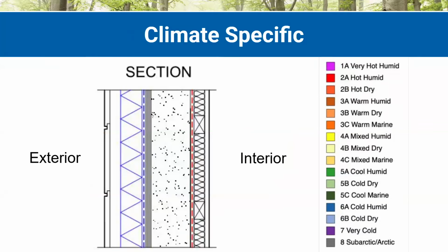I'm now going to be running through this wall assembly where we have the exterior side on the left and the interior on the right. From the exterior coming in, we have our siding, our rain screen, our exterior insulation as vapor open. We have our house wrap, our sheathing, then our cavity insulation, whether that's a batt or a blown in, then our interior air barrier in red here. This could be the Intello membrane, the Intello Plus or the Intello X.